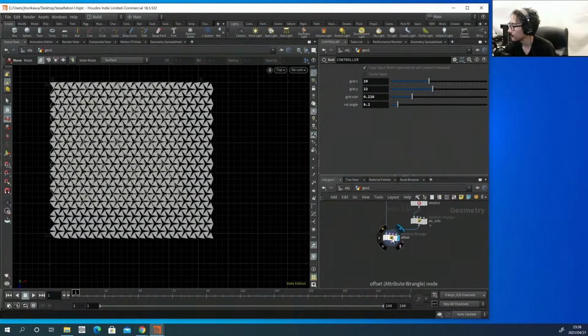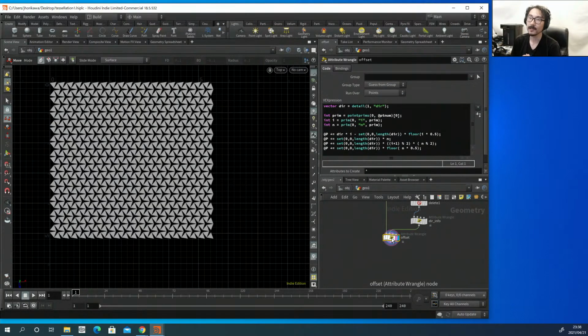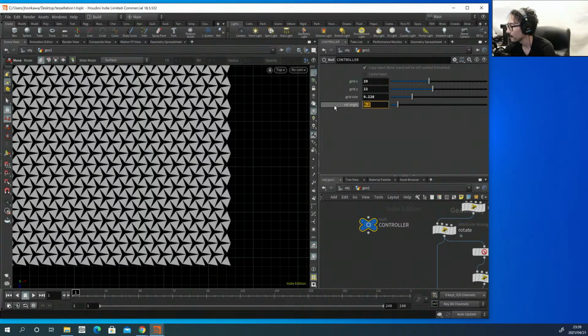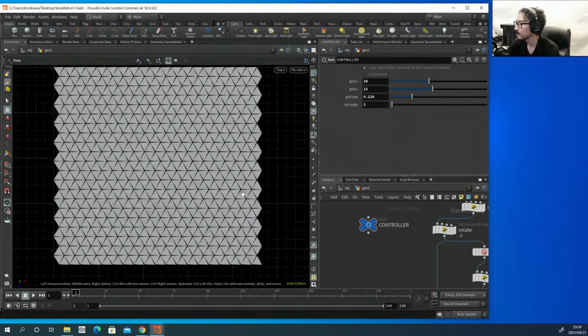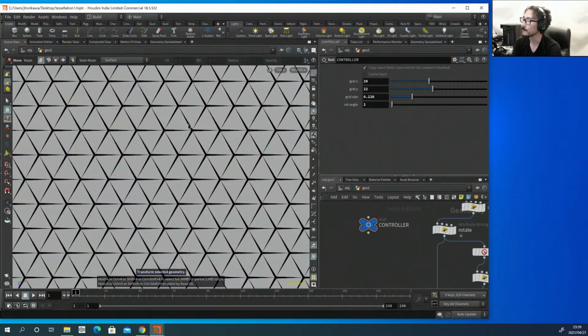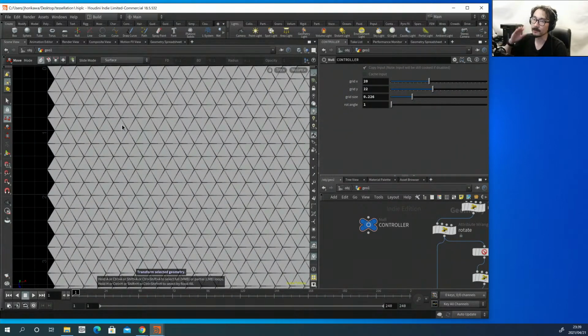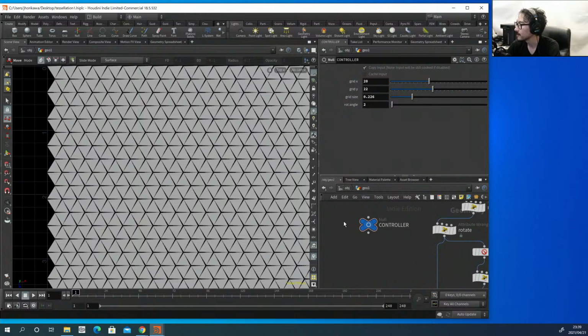All right, now let's go to step 2 of phase 2 to make it physical, to work with the Vellum. And that's what I wanted to do initially. Takes a lot of time till here, but I think it is worth it. First thing I would like to do is to make the initial geometrical tile have a small angle as possible, like 2, 1, because I want to start with a really planar surface, then make those patterns open with specific collisions to have an interesting effect. So let's make it 2 for now as initial condition.